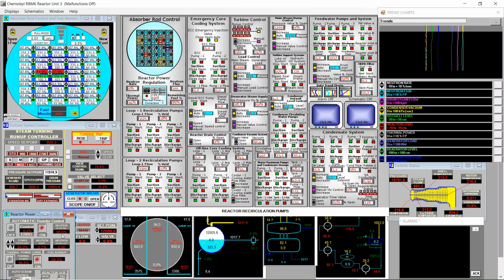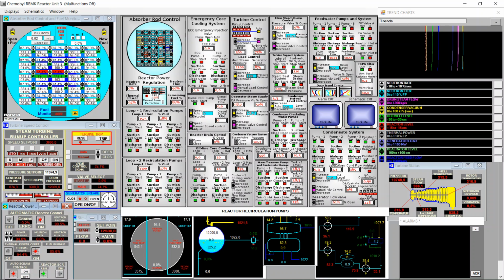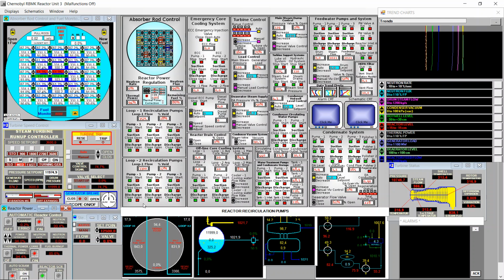We're at 99.6. I didn't expect this 6, I expected a 5. So now, unless the neutron flux goes below 99, I will not increase again the power set point. And we see the generated load is at 874.5 megawatts. Now the turbine is behaving very well, low vibration. The differential temperature between the shell and the rotor is almost none, just 3 degrees. The rotor is at a bit higher temperature, vibration at 8%, and it seems it's decreasing.